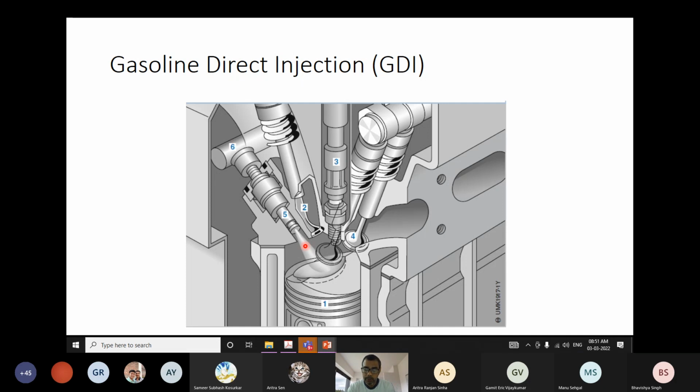In a gasoline engine with liquid fuel itself, when you have to inject, you have wide flexibility. You can start as soon as the intake stroke is initiated, and you may end the injection before the spark is created. So you have almost all of the intake stroke, and also most of the compression stroke. With such wide flexibility in when to inject, you are going to optimize the engine.